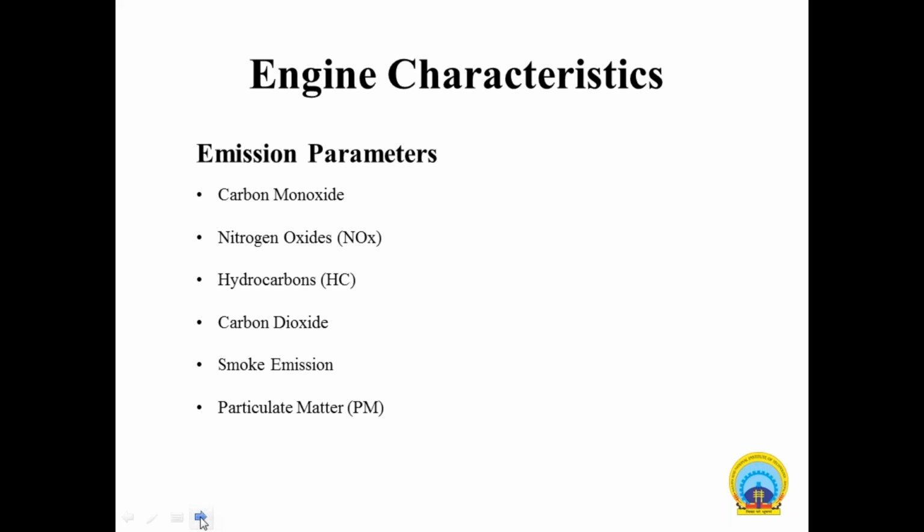Then hydrocarbon is there. Unburned hydrocarbons are the hydrocarbons emitted after petroleum is burned in an engine. When unburned fuel is emitted from a combustor, the emission is caused by fuel avoiding the flame zones. Then smoke emission in the diesel: black smoke appears during disturbance in the high pressure pump injector and at a high angle of injection.